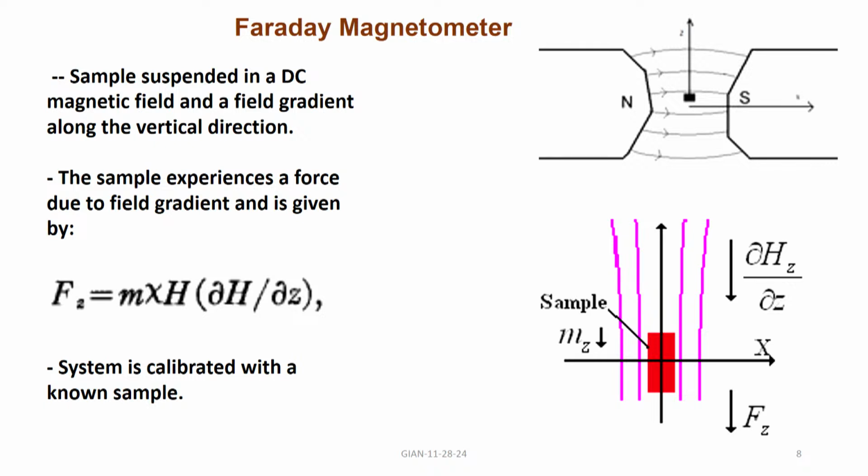When you do that, there is a change in the magnetic field produced by the coils in the vertical direction that will produce the force. So, it is rather easy to do compared to shaping the pole pieces into a parabolic shape. That is rather difficult to do unless it has special machining.